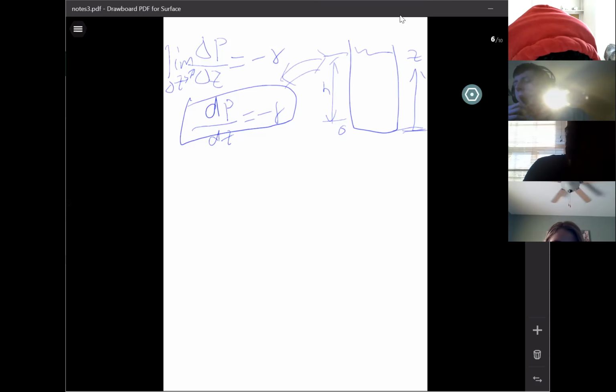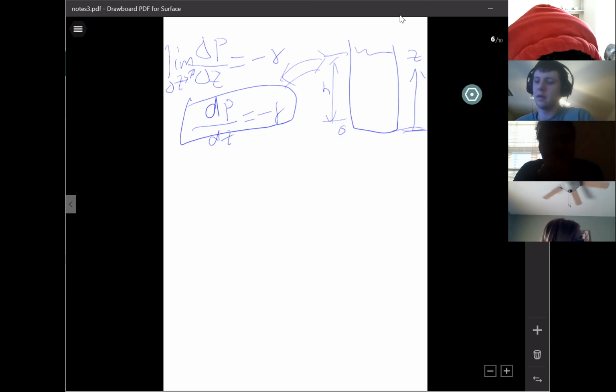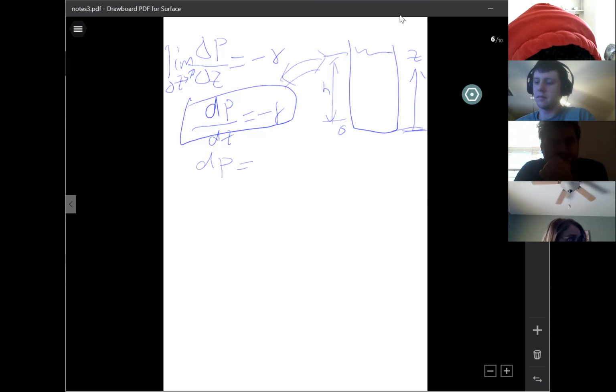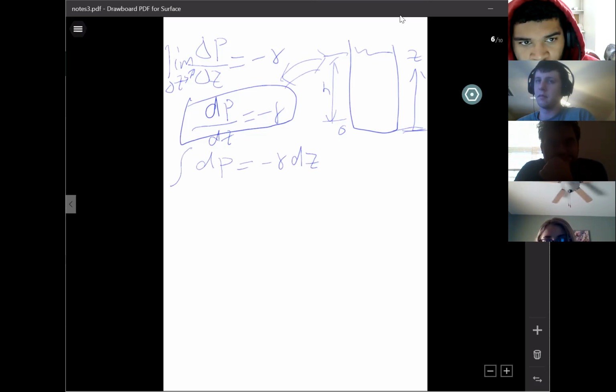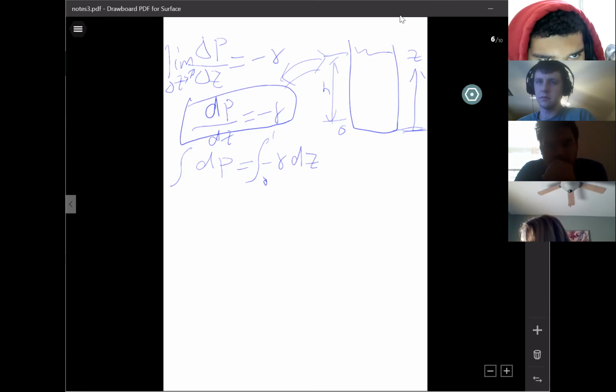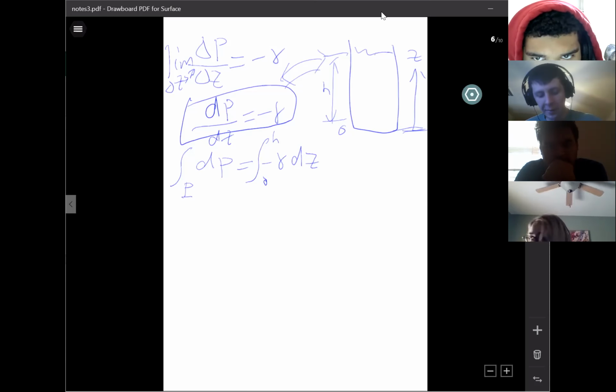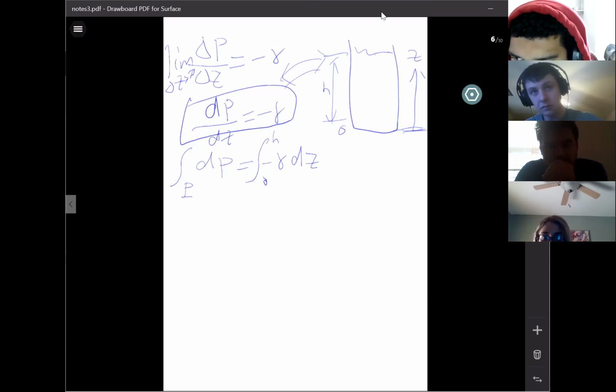So now can we solve it? Yeah, we can solve it. That's easy, right, everybody? There are different ways to solve this. You just take integration, right? If I were you, what I learned is, I move the dz to the right-hand side, then I take integration. Is that what you were taught? So Z goes from 0 to H, that's the range for Z. For P, the range is from the pressure at the bottom, let's say a capital P. What is the pressure on the top? Delta P or P plus delta P?